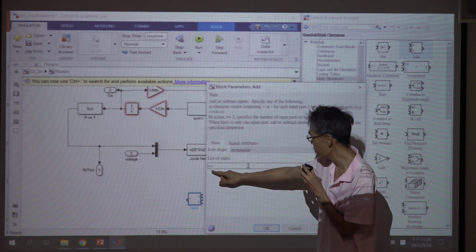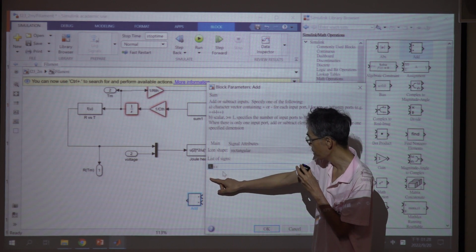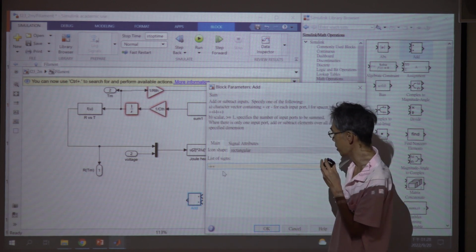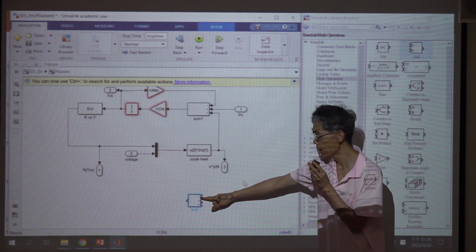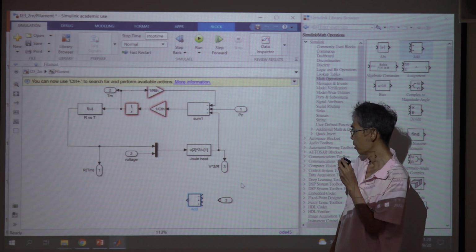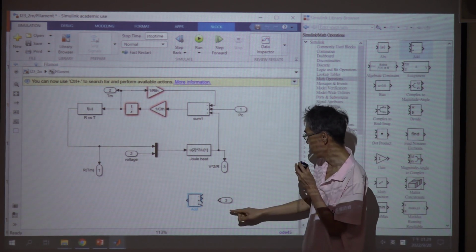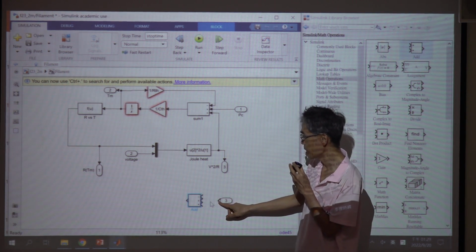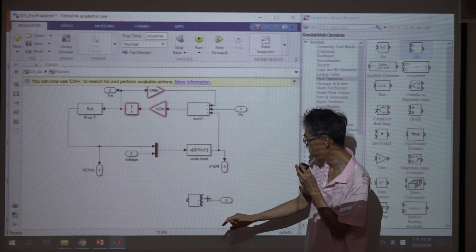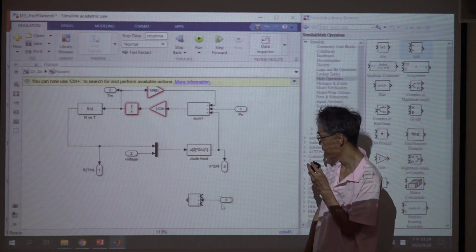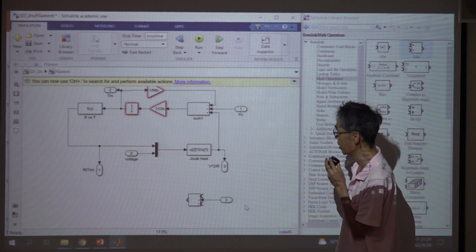So double click, you can add one minus sign before the two plus signs. So move your cursor. Minus, yes. So you can have one minus, plus, plus. And if you want to drag the signal line, you can left click here and hold your mouse and release. So you can create this signal line.